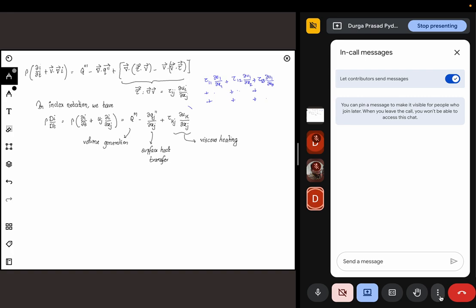So if I have my continuity equation, which says u_x plus v_y equal to 0 in 2D form, you basically have only two variables. And now I'm introducing another equation where I have tau. This is an additional variable introduced without an additional equation. In this particular equation, I'm introducing internal energy and tau, two terms, so I will not be able to solve this unless I have one more equation for tau. And that is where the constitutive equation comes in.